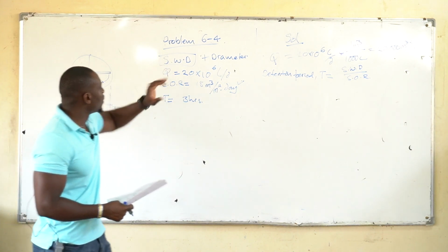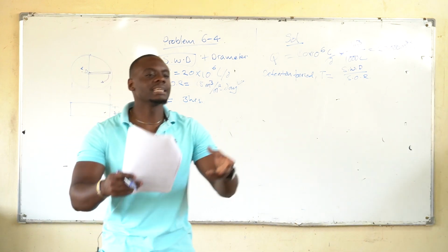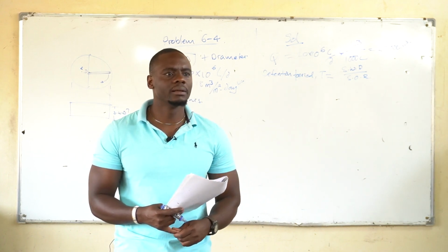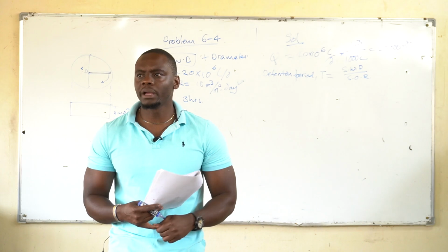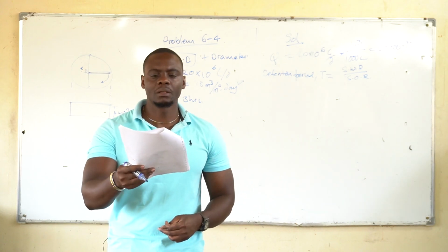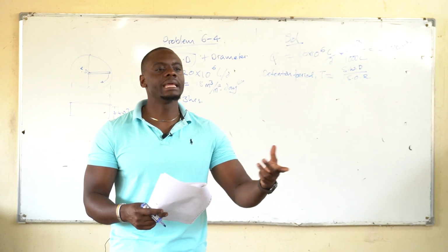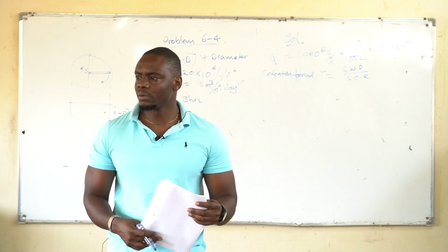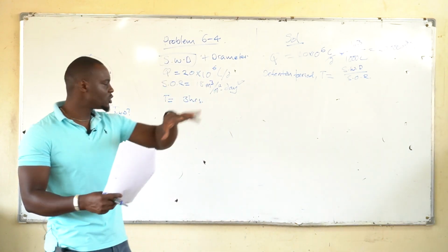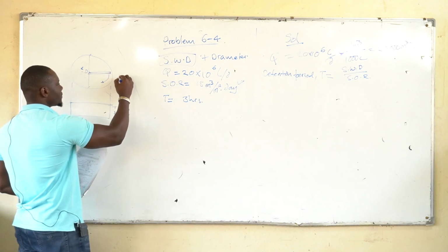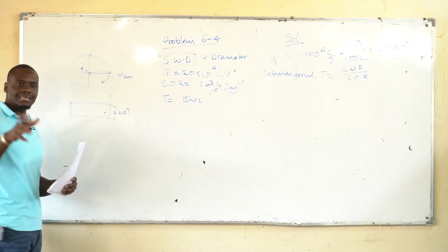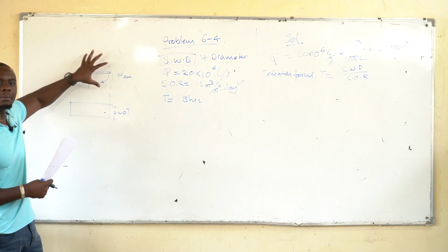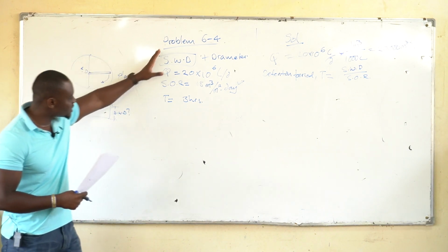Okay. So whenever we're dealing with a settling tank, settling tanks come in different shapes, right? It could be a rectangle, it could be a square, it could be circular. But whenever the question says find the diameter, then you know you're dealing with something circular. You have seen the clarifier before? Yes. So from the top, this is what I've drawn here. So as a plan. They are interested in you determining how big this settling tank should be by diameter, given these parameters that are coming in.